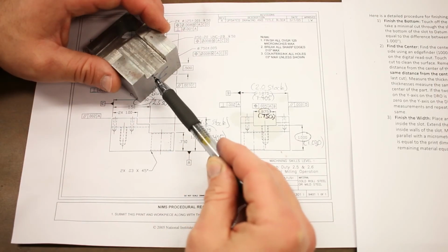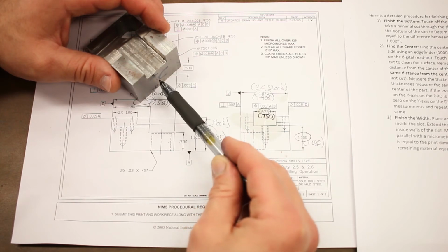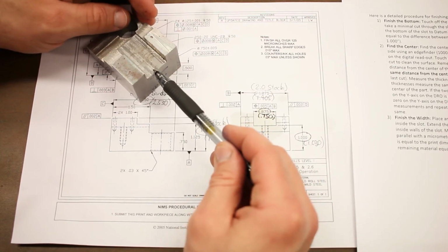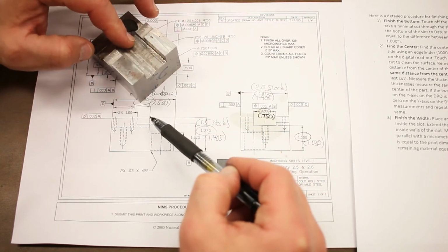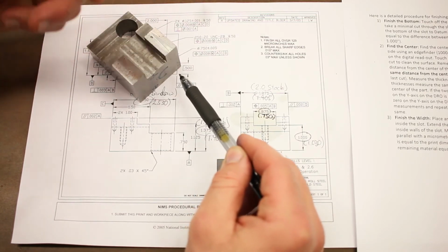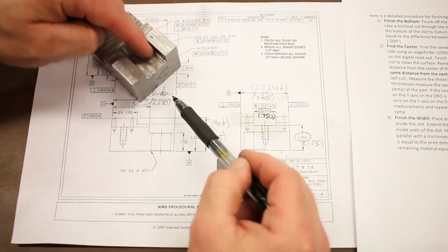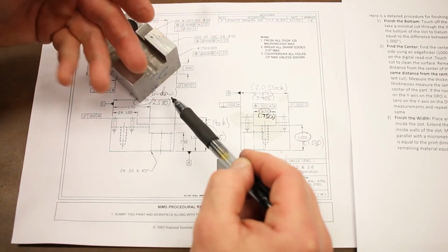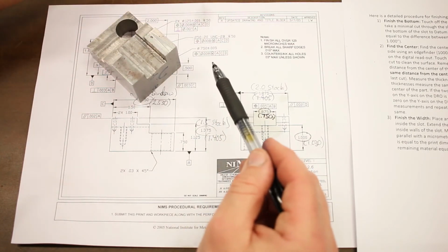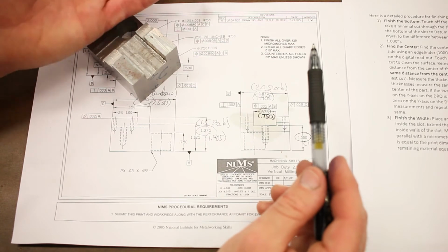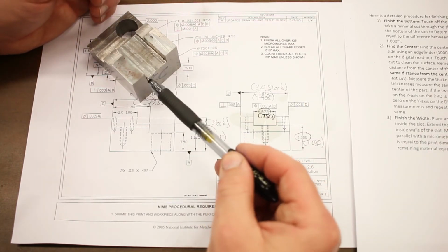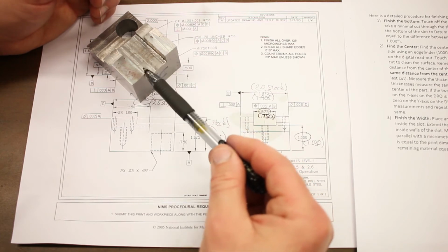Finishing the 1-inch dimension relative to datum A is a pretty easy thing to do, right? Just like we did with the steps, all we have to do is take a pass right through the center of the slot, some minimal amount, measure it, adjust the position of the knee, and then just forget about it. Because in the process of cutting the 2 sides of the slot, we're going to be passing over the bottom of the slot several times, and so it's going to come out to wherever we position the end mill with the knee of the milling machine. Easy enough.